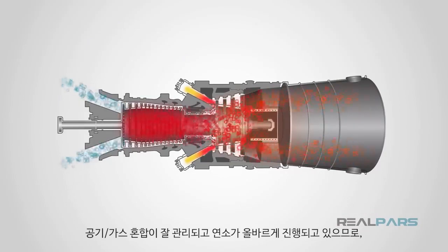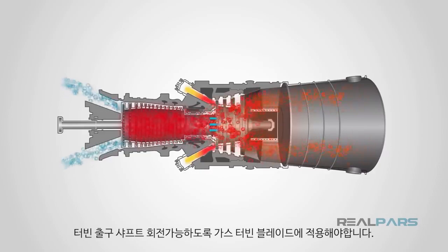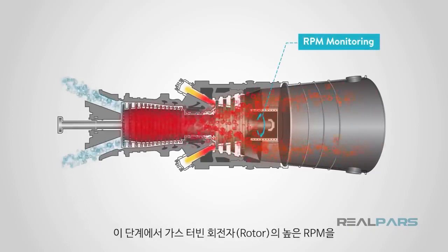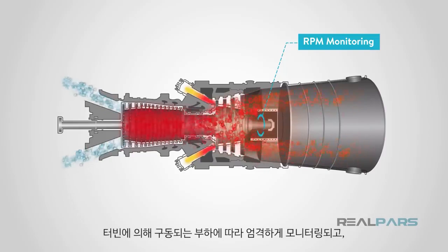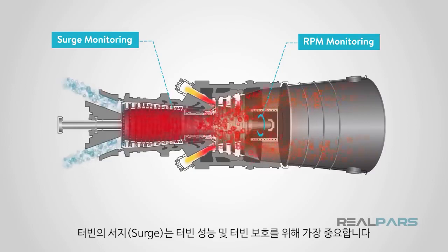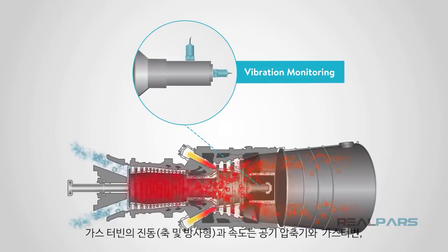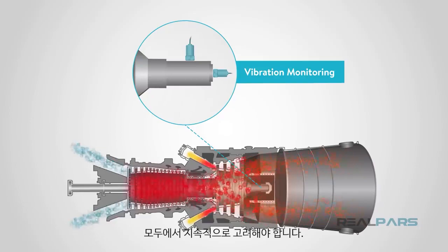Now that the air-gas mixing is well managed and combustion is going on properly, there is plenty of high-pressure, high-temperature exhaust gas generated and it should be applied to the gas turbine blades to make turbine exit shaft rotation feasible. At this stage, the high RPM of the gas turbine rotor should be tightly monitored, and based on the load driven by the turbine, the surge of the turbine gets the topmost importance for turbine performance and turbine protection. Vibrations, axial and radial, and speeds, both at the air compressor and gas turbine, should be continuously taken into consideration.